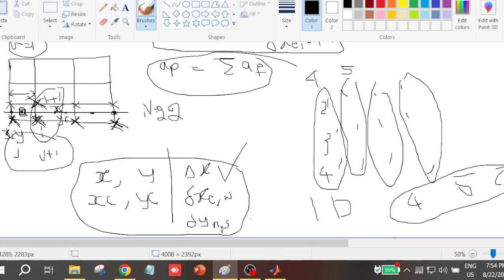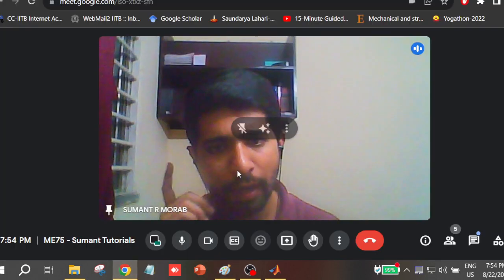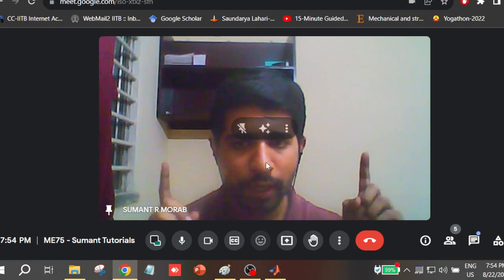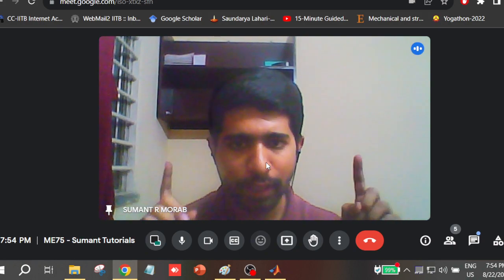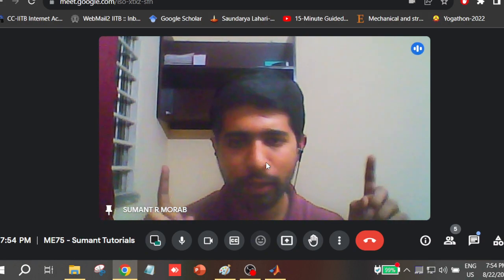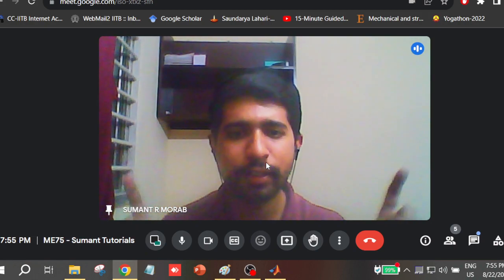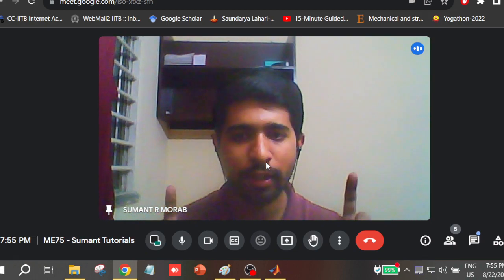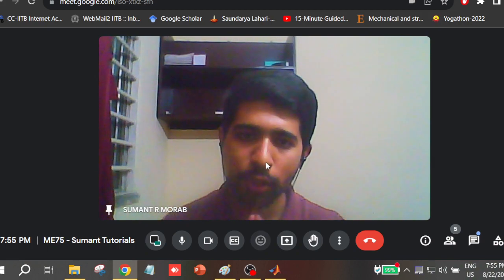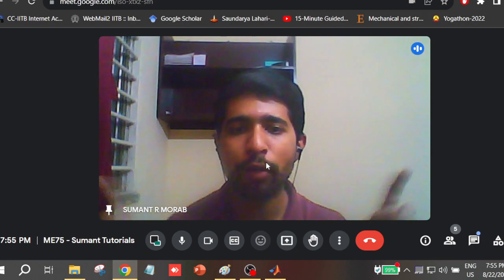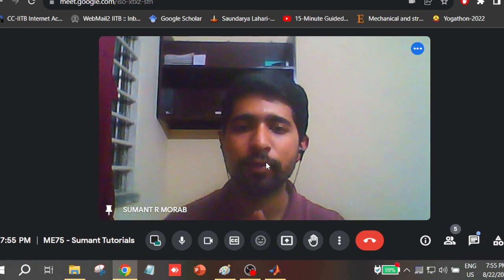No, no, no. If you have a temperature fixed at the left end and a temperature fixed at the right end, that is your case, right? 400 and 100, whatever it is. And if you do not have any heat generation in the problem, then it should be bounded. It should be within the 100 to 400 range. It cannot go beyond that.